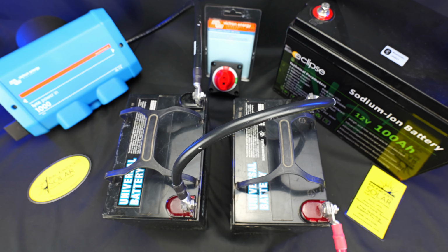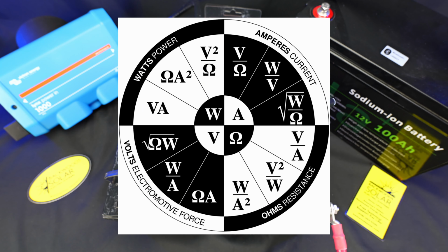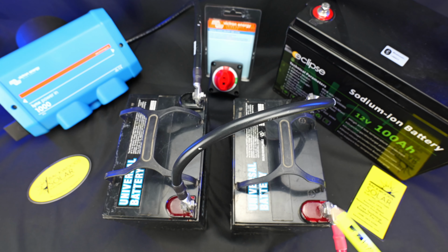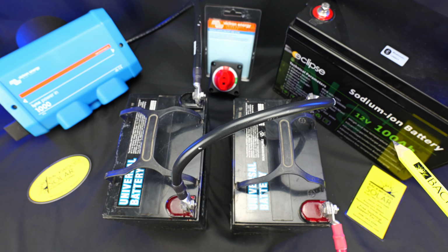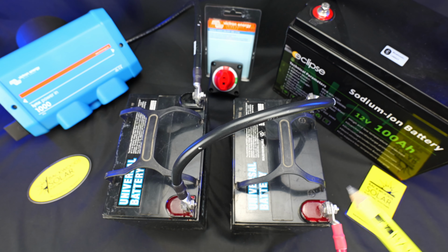The reason it's so exceedingly important with lithium or sodium is that they have low resistance internally. So any slight differences in external resistance, cable length, diameter, corrosion, may cause favoritism throughout the group or strings of batteries to occur, where the battery with lower resistance may do more work, more total energy in and out over time.